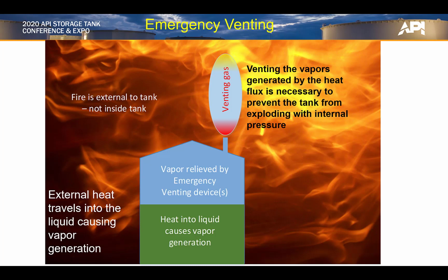A word about flame arresters required on tanks. This quote comes from API 2000. The petroleum industry has had good experience with tanks protected by pressure and vacuum vents without flame arresters. As a result, there has been a belief that this good experience is due to the pressure vents' potentially inherent flame arresting capabilities. Recent testing, however, disproves this hypothesis, at least for the tested conditions.